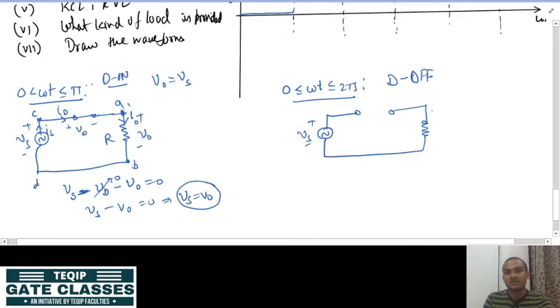Vs, I naught, V naught, R. Now, here you can see when the diode is off, the circuit becomes like this, an open circuit. In this case what you are observing is that there is no connection between the load and the source. So, when there is no connection between load and source, obviously load current will be 0, and when load current is 0, then obviously load voltage is also 0, because R cannot store anything across it.